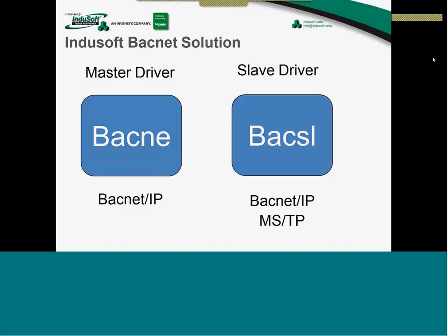So, for example, like I said, if you want to implement a low-cost gateway, you can use Modbus and BACnet. The Modbus driver reads the data and puts the data on the BACnet slave. And then, with other software, you can read the BACnet slave as if it is a gateway.